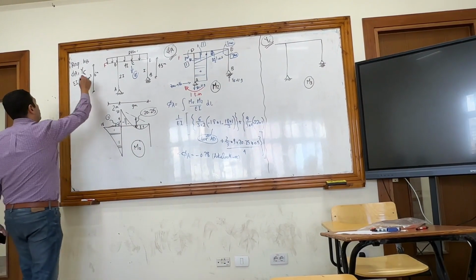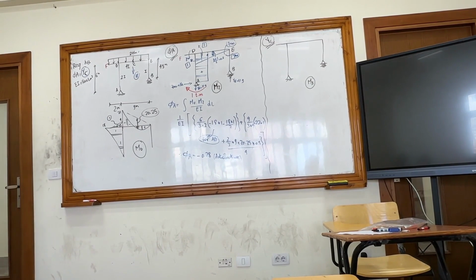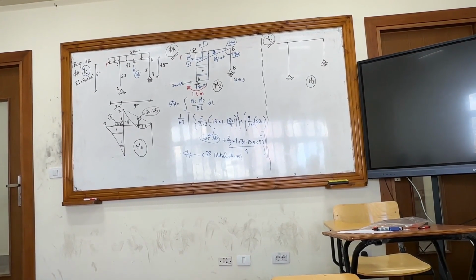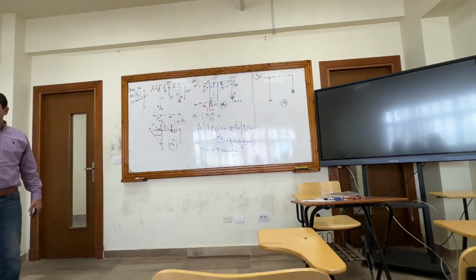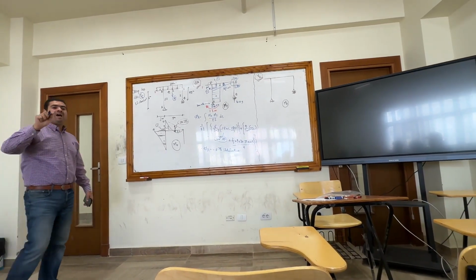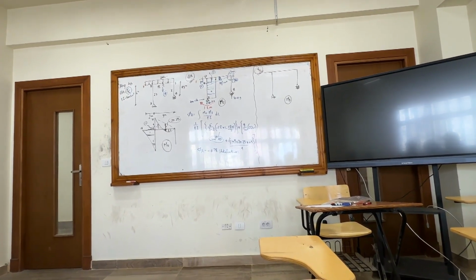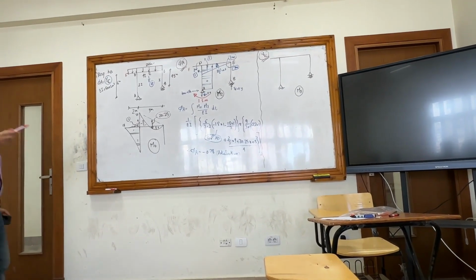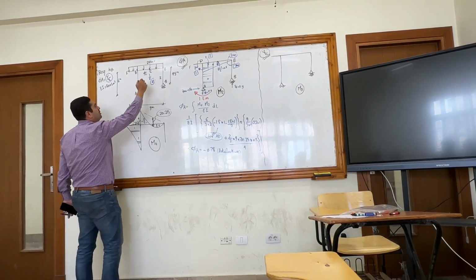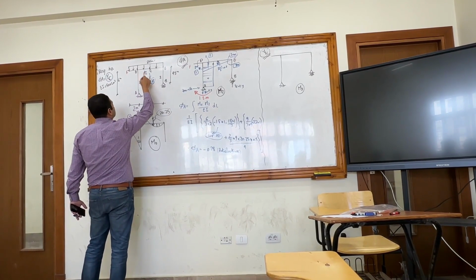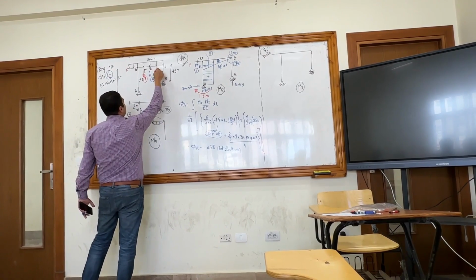But for this one, intentionally, this will be wrong. I am asking you to calculate a displacement inside a distributed load, so you have to draw the M node one more time, and you can't put the 18 here. You have to distribute it, 2 times 4.5, 9, and 2 times 4.5, 9.